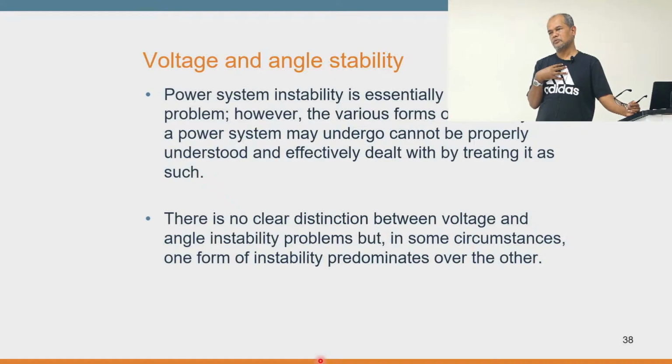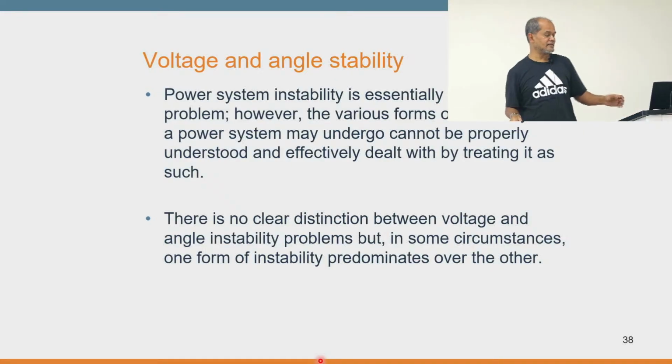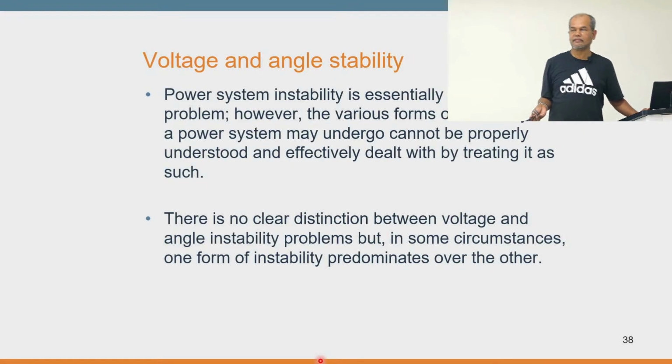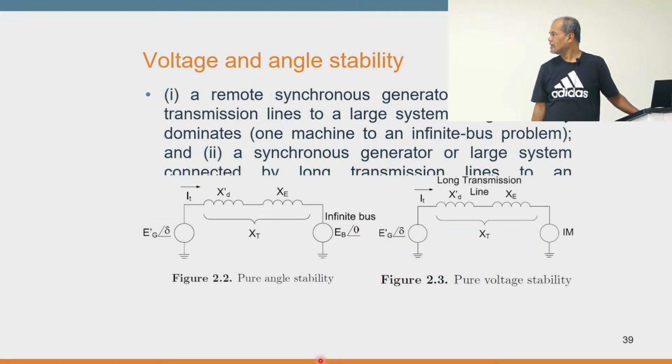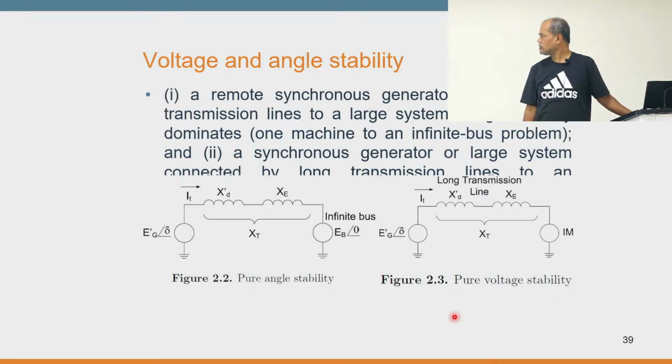But again, as I said, once you work in the power industry and also do research, from your experience you might tell what actually causes the system to become unstable. Even from the power system configuration, sometimes you'll be able to say. If your system has a generator connected with an infinite bus or in a big power system, your system will never have a voltage stability problem, because the generator has the capability to control voltage.